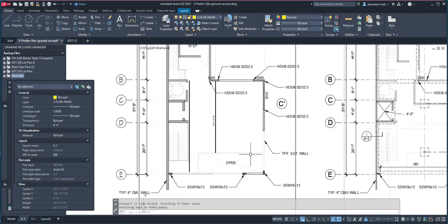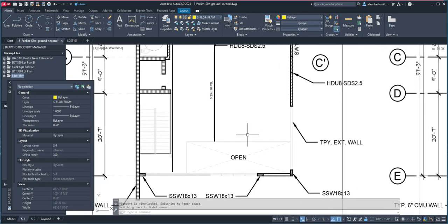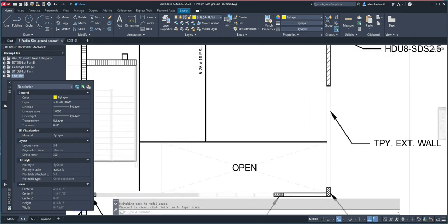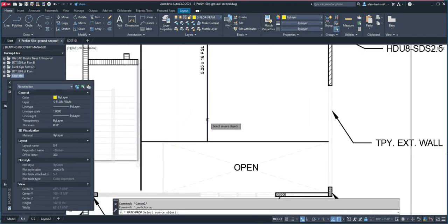In order for this opening to be created, a beam must be supported. There's a column over here, and that's good. But we're going to have a beam going through here, and we're not going to stop it here and turn because beams really don't turn. Actually, it's anchored to this other hefty beam here. So we're going to do another P line, click here, and do a perpendicular line up to here. There you go. And we're going to match properties with this and here.